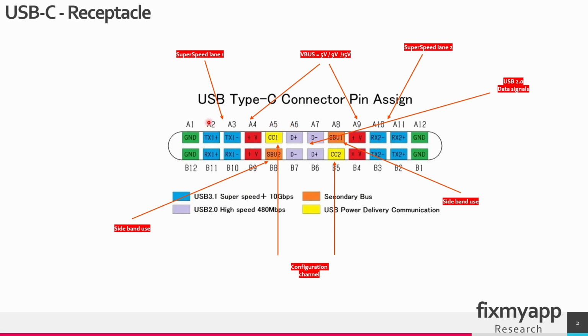Also a key feature of the USB-C port is its reversible design. The connector can be plugged in either way, making it convenient for users. So we don't have to look at the orientation of the cable, we can just plug it in, and the cable will make contact to one of those rows. If you look at the first pins, when you rotate the cable, those pins are mirrored on the bottom side.